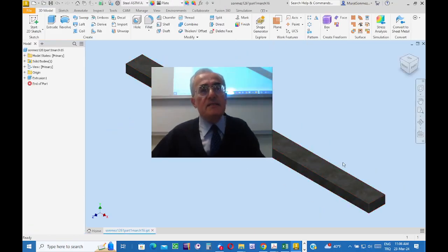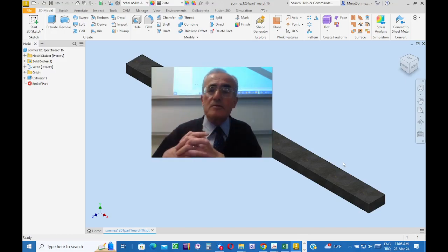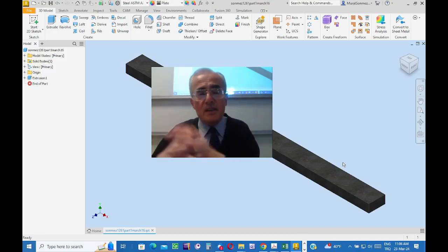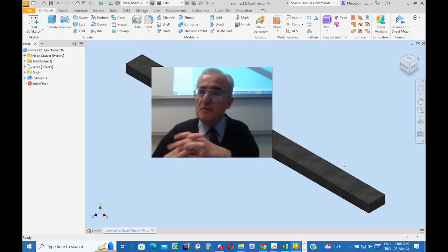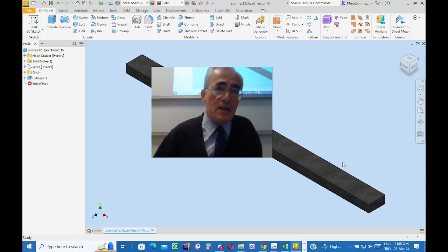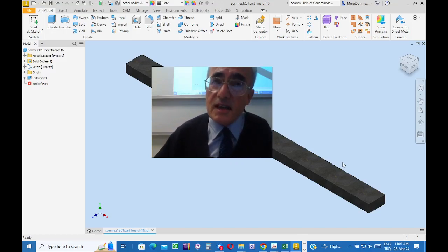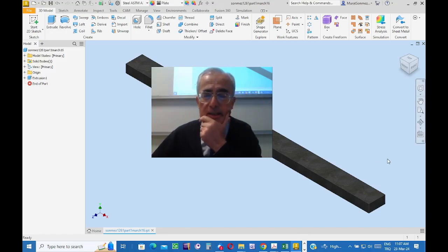You know, we selected in the first session a very simple problem for which we know the analytical solution. For verification purposes, we did it. We know the analytical solution, and then checked using the tools of Inventor and also Nastran whether the stress values, strain values, displacement values, and factor of safety values are the same. And the answer, yes, was the same. So the software solved the problem correctly.